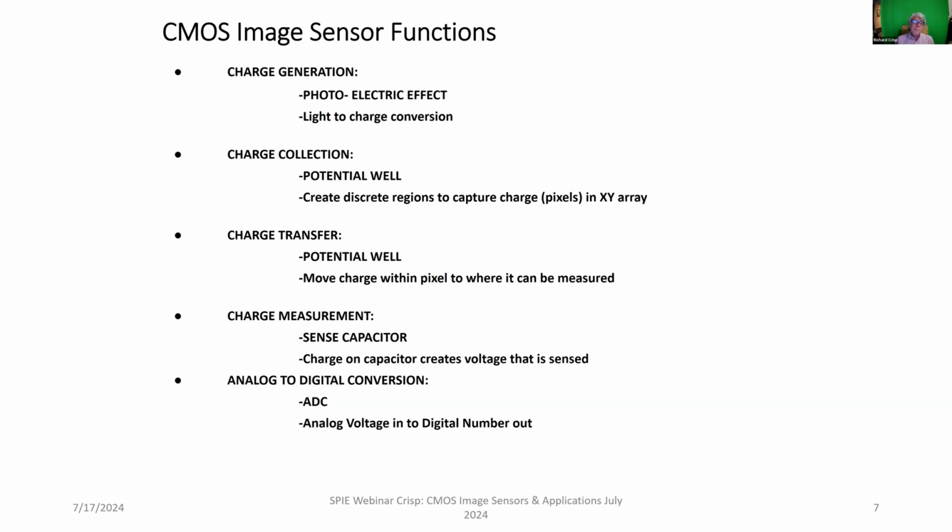It's simply not practical to do it in a CCD because they're generally all one polarity of transistors. So it's either an N channel or a P channel type array. And so there are not both P-type transistors and N-type transistors. There's generally only one flavor of transistor.